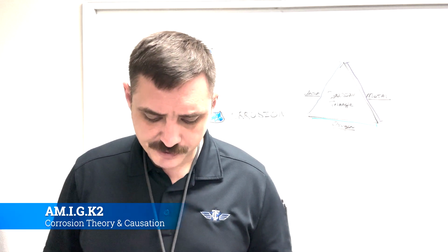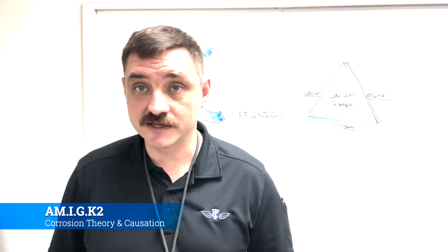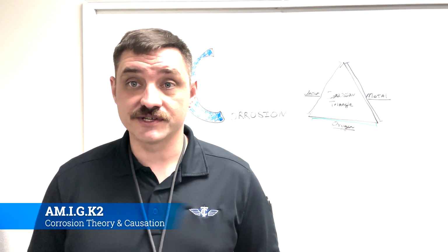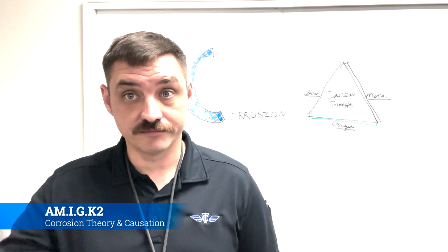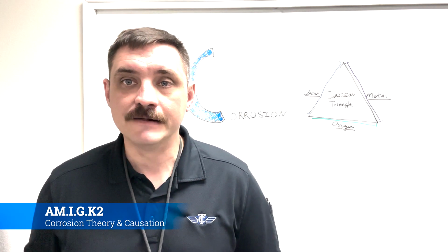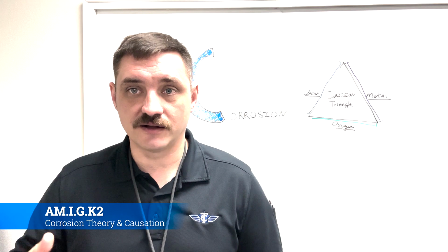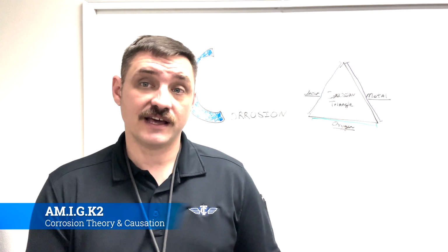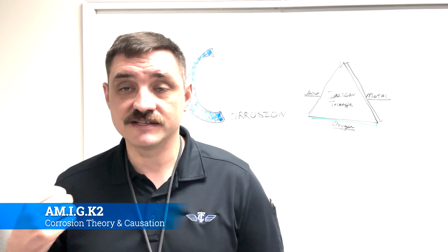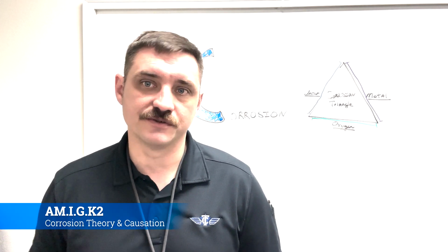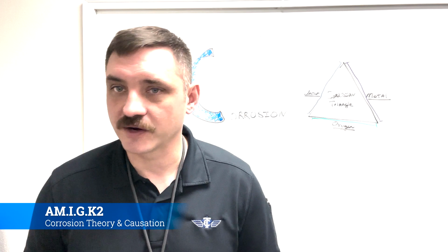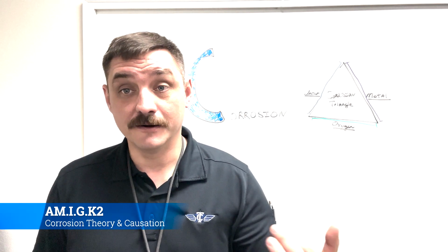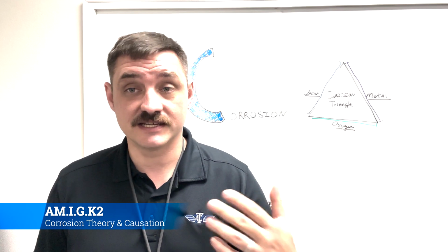Okay, time of exposure to a corrosive environment. So that goes back to the engine washes. That's a time of exposure type thing. As it flies within 10 nautical miles of a saltwater body, then you're exposing it to that super salty air. The salt inside the air just adds to the corrosion. It's more or less like sucking up a very weak battery acid, really. And so you are exposing it to that area.